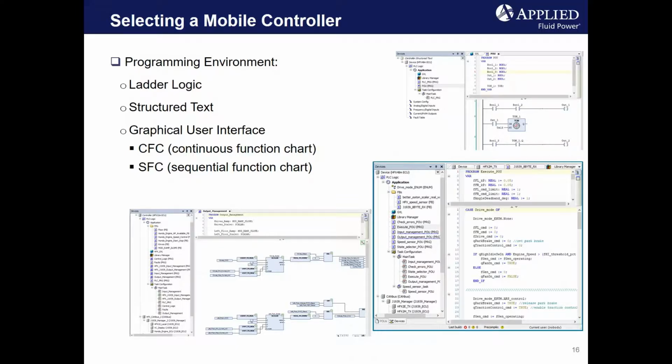The Codesys software that is used amongst various controllers offers a variety of languages such as ladder logic, the traditional graphic programming environment, structured text, which is logic just written strictly with text, something they call continuous function chart, which is a graphical programming interface that lets you drop in functions and function blocks and connect the lines and variables to them, or sequential function chart, which is similar to continuous function chart, but essentially is a graphical programming interface that creates logic in its sequential order.